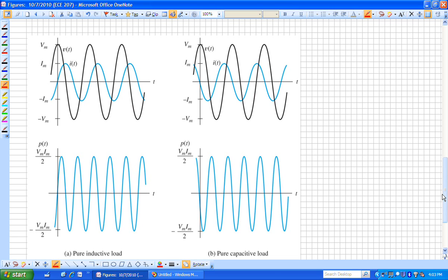Conversely, if we look at the capacitor, what's happening? Now let's go over to the first peak that we see, and the blue is peaking before the voltage. So the current leads the voltage in the capacitor. And that's how we experience voltage and current leading and lagging in inductors and capacitors. I got too much into the experience. Does that help?